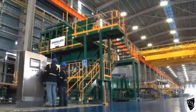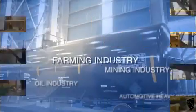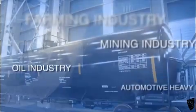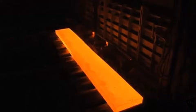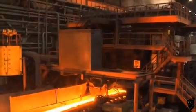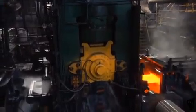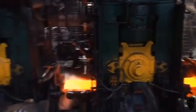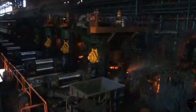AMSA is the only manufacturer in Mexico that produces steel plate, which is used for making farming and mining machinery, oil industry machinery, as well as heavy automotive and railway products. On the hot strip line, the slab is processed for the production of hot-rolled coil. First, the slab is reduced in the universal reversing mill to a thickness of 2 inches, and then on the M stand it is further reduced to 1 inch. The final thickness required by the customer is achieved on the 6 standing roll mill train.